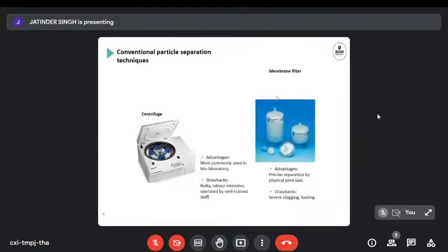Traditionally, particle separation can be done with a membrane filter. So you just have either a cross flow or a tangential flow filter. You push the liquid through and the permeate is particle free. Another thing that you can do to separate particles is centrifugation based on different densities. The higher the density of the compounds, the deeper they will sink down into the centrifugation tube.